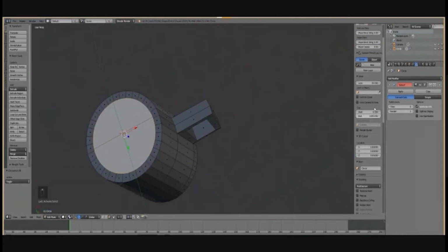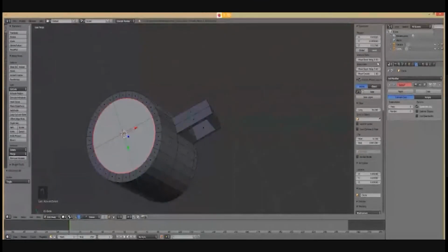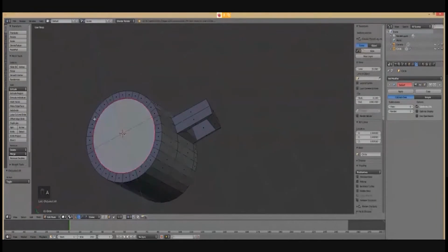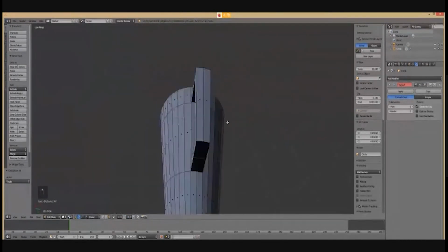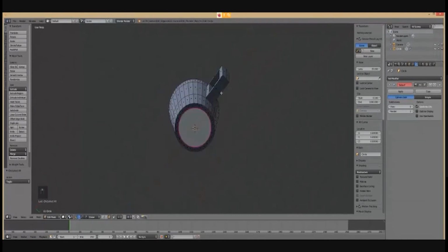In this tab, at the top of the tab, you will notice that there is something called a mean crease, right? I'm going to select this mean crease and change its value from 0 to 1 and click enter. The moment I change its value, you will notice that the boundary of this bottom surface has become purple. I'll explain what mean crease does in a bit, right? So what mean crease does is, even when you're applying the subdivision modifier, essentially when you're making it smooth, if you apply mean crease anywhere, mean crease basically maintains the sharpness, right?